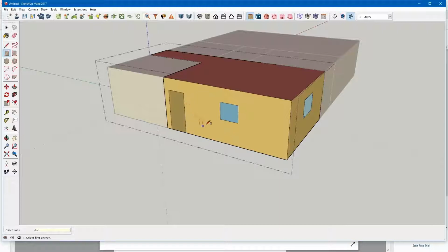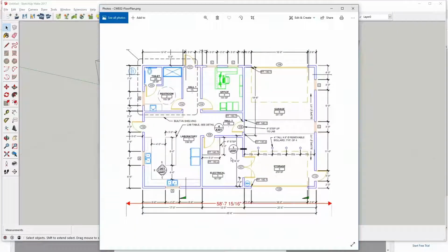There. It's a door. So if you want to draw doors, you always start at the bottom edge. That way OpenStudio knows that you're drawing a door. If you want to draw windows, you draw them detached from the edges. That way OpenStudio knows you're drawing windows.